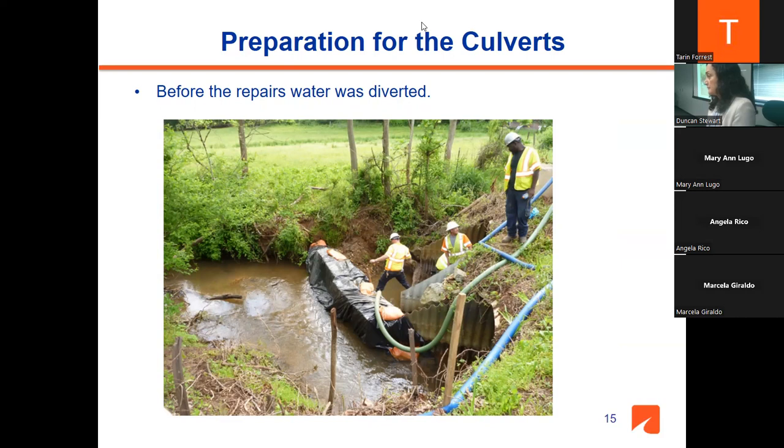So I don't know whether they are using recycled materials or not. The steel fibers that we use are very common, domestic fibers. They are using a lot of those hooked end fibers in tunnel linings and buildings. So all these fibers are domestic. We have to use Buy America, which is very important for VDOT. But I am not sure whether the manufacturers are using recycled material for those. We are not sure about that.